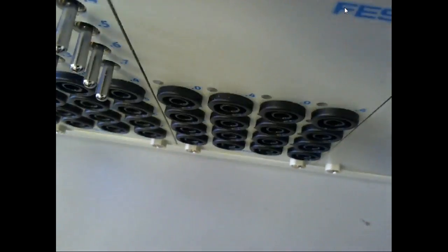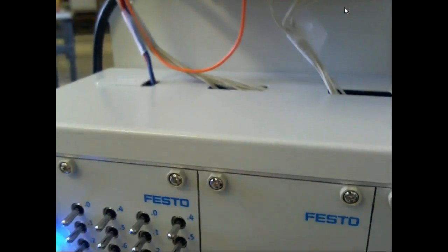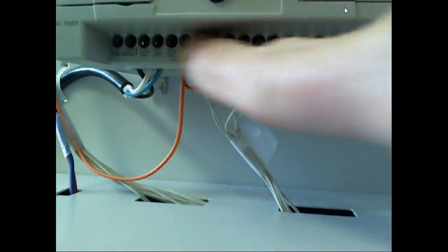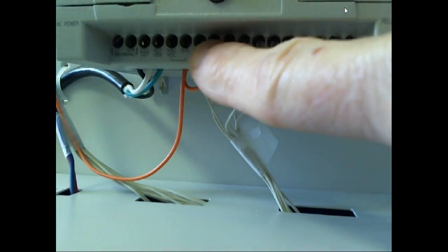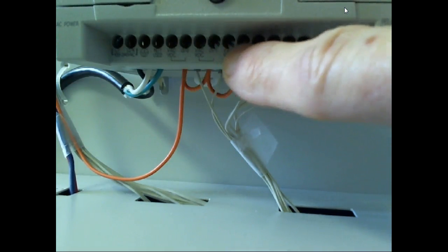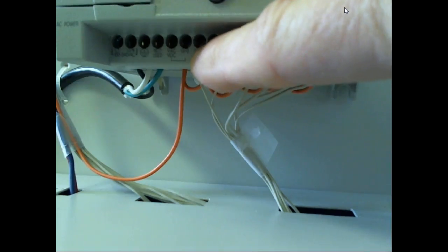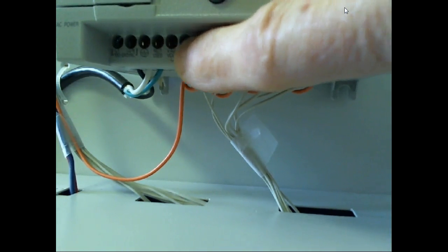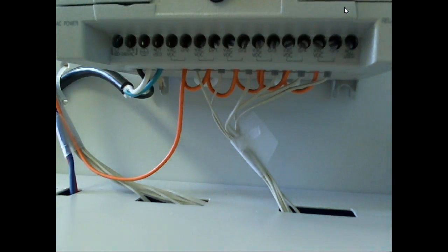Now my outputs, if I can get my camera up here, what I've done on my outputs is I'm bringing, don't pay any attention, this is the only color wire I had. And so this is the positive on my outputs. And what I've got on this one, the way this is set up, this is a relay output, and it gives me the ability to hook up DC, I can hook up AC, I can do anything I want to. But what I have right here says a common. And then I've got this jumped to all the commons. So what I have is the positive of my power supply hooked off to the common on my outputs, right? You understand?